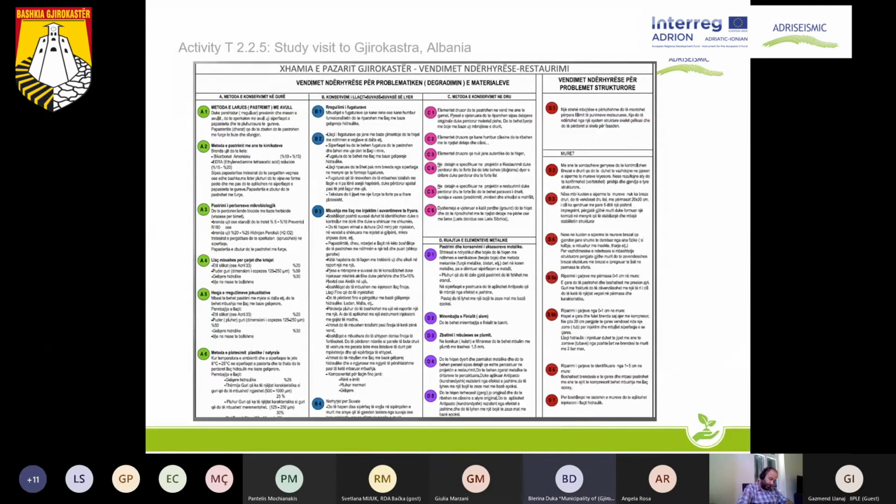So, just a brief explanation for the wood conservation methods under the C letter and purple color. The wooden elements in total will be cleaned on the construction site, so in the dwelling itself, and then the old parts will be repaired with new parts according to the same methodology of woodworking, so chiseling, and also the wooden material. And the wooden elements which have lost their quality will be done again, as I said, using the same details and qualities.